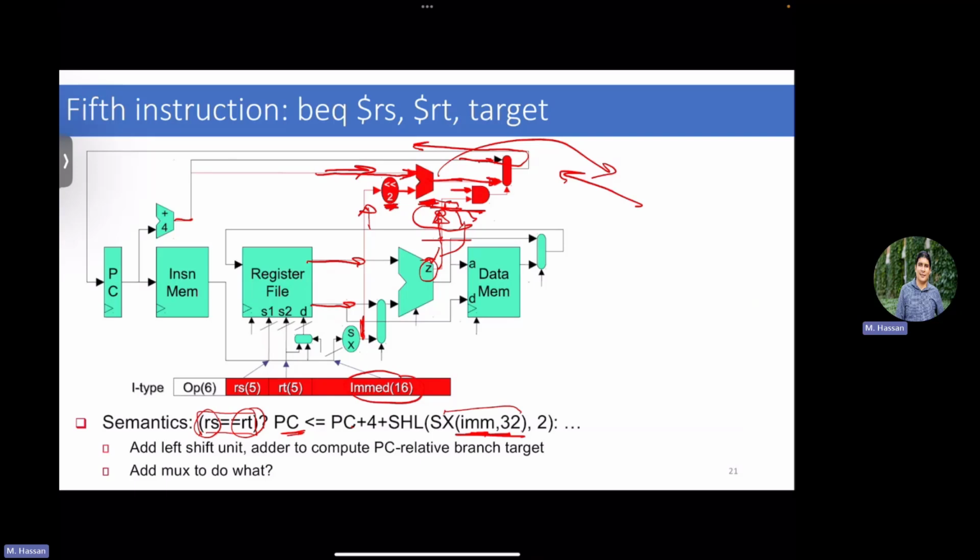You have the jump. You have the branch if the condition is true, and you have the branch if the condition is not true. In case of a branch with the condition not true, or the normal path, you just increment the program counter plus 4, which is happening here. In case of a branch with the condition true, you load in your added offset to the program counter. In case of a jump, you take the immediate value directly and load it to the program counter.